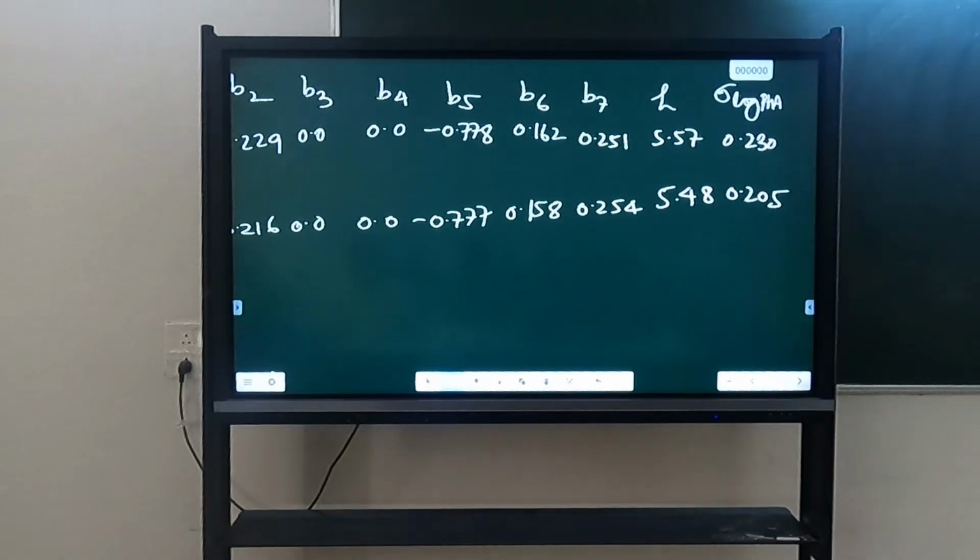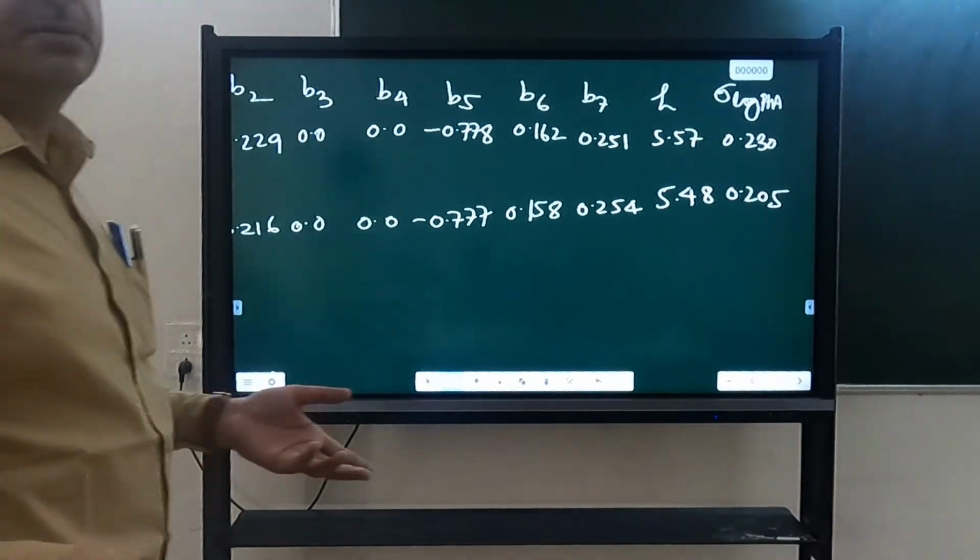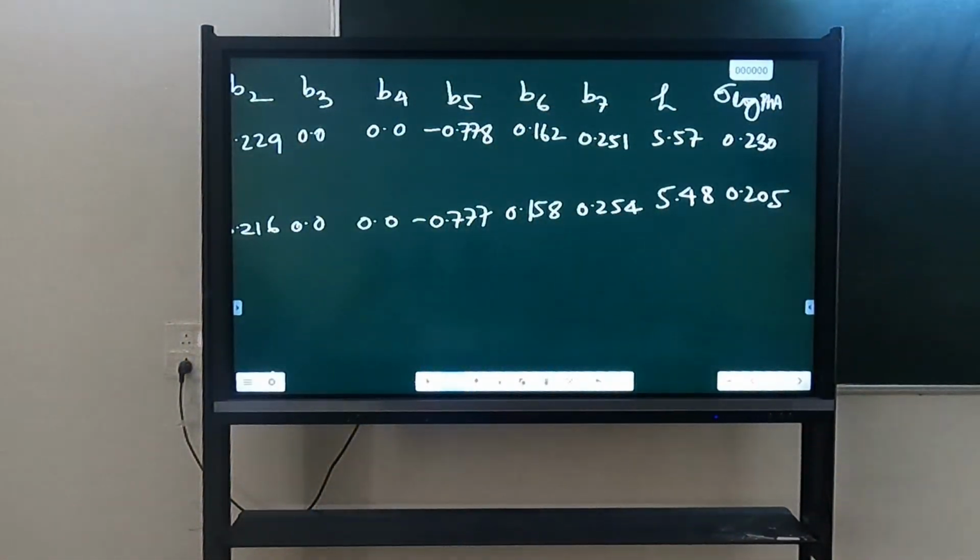It depends on your objective, whether you are developing for all the components of earthquake, or if you know the direction, then the larger component. To be on the safer side, use larger. If you know that the component which will be coinciding with the direction of your building is larger, use larger. If you are not sure, use random, which considers both.